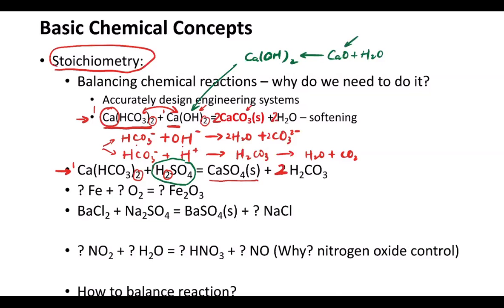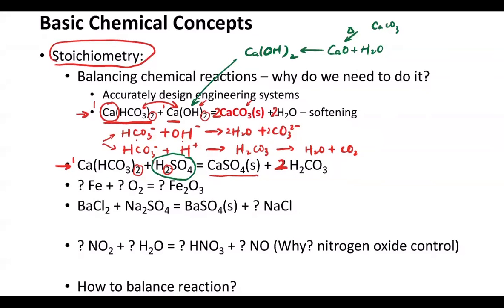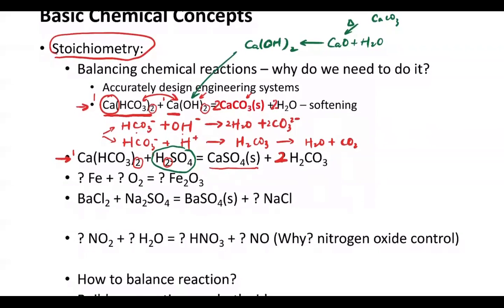So we can go to mines and dig a lot of rocks, and most of them are limestone. And then by just heating up this limestone to, let's say, 1000 Celsius, we're going to form this calcium oxide, which means that it's very cheap to produce these raw materials, right? Because it has a low price, we can directly use it in water treatment. But for the sulfuric acid, you probably need some complex method to form the compound, right? So that's why we use this method for softening the water.